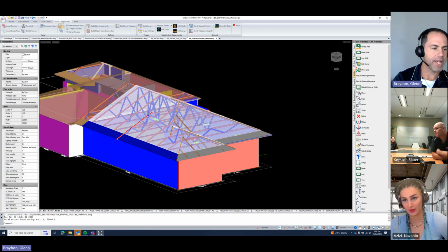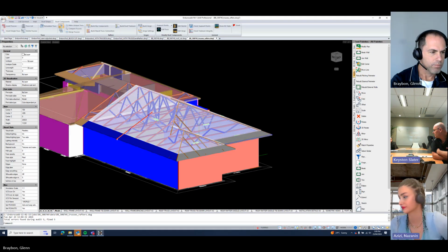Is that something you could put into an EH? Possibly. I think you mean if there is no top chord, it won't build the outriggers, right? So you have to add a beam so it'll add the outriggers. Instead of the beam, we just extend the top chord of a truss to act as a beam. But when you design it, it won't consider that into account.